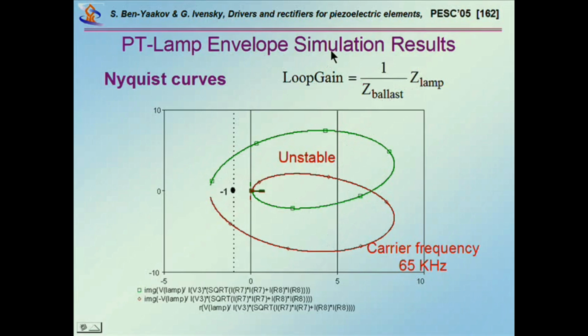So what we see here is that the crucial parameters are the incremental impedances of the elements that you have to look at by envelope simulation, or by some other means, not the total impedance of, say, the piezoelectric transformer.